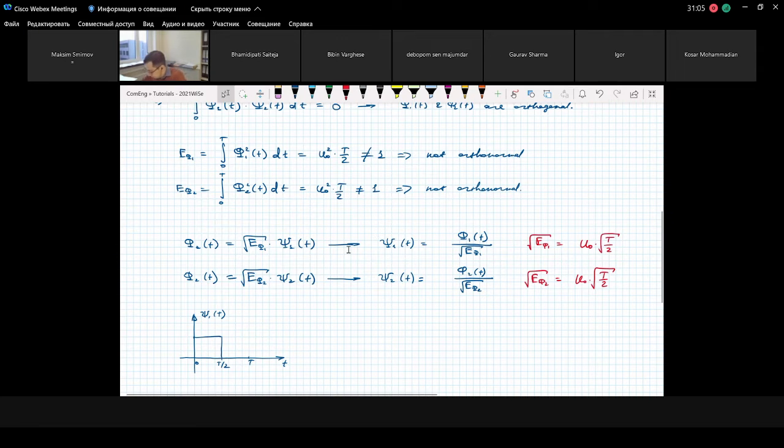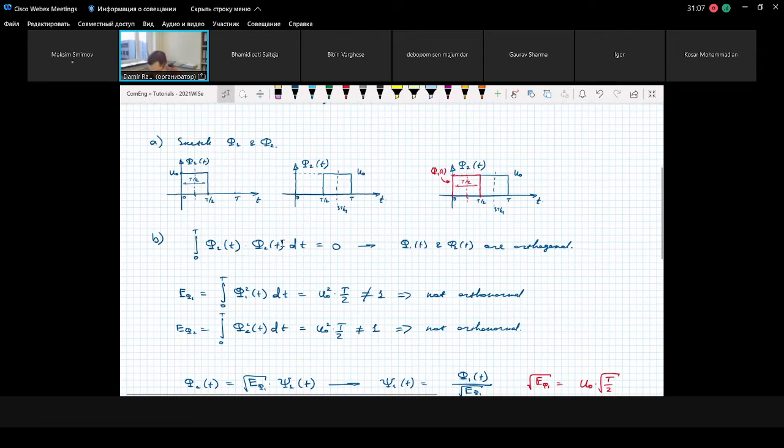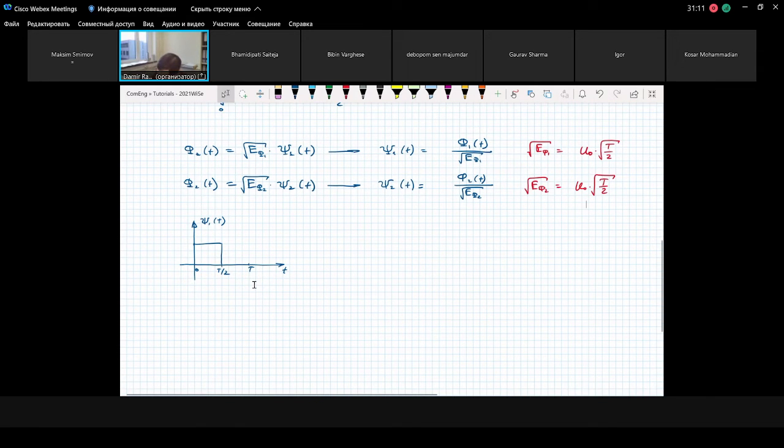And now we need to divide by this quantity, the amplitude of the original pulse shape. And then we get something already familiar to us. We get that the amplitude will be 2 over capital T for both basis functions.